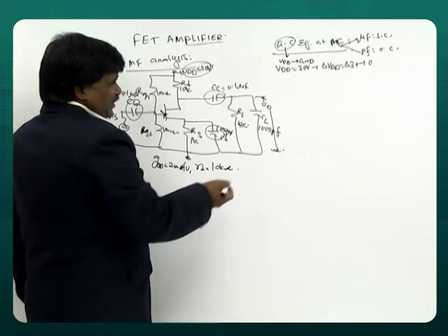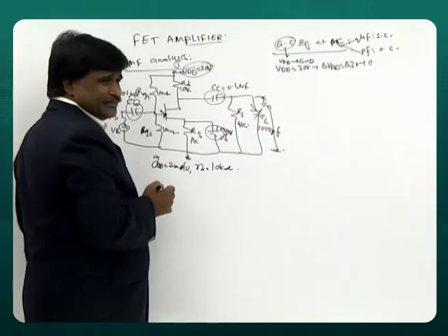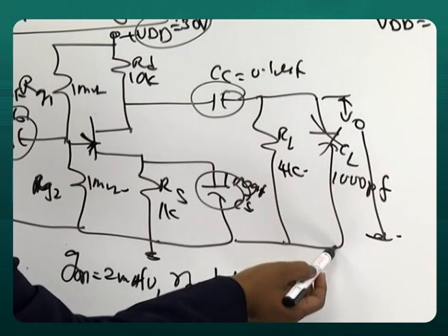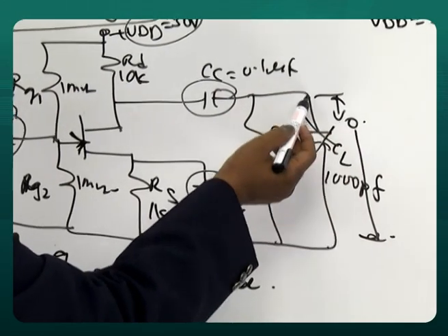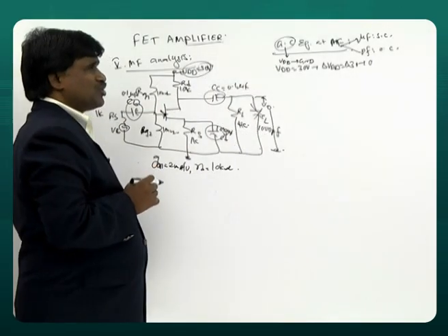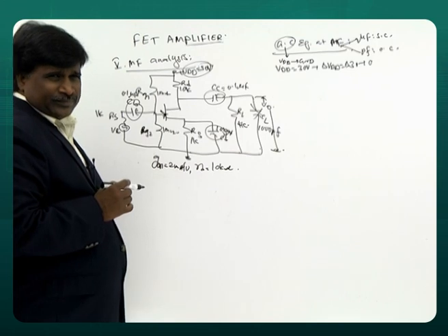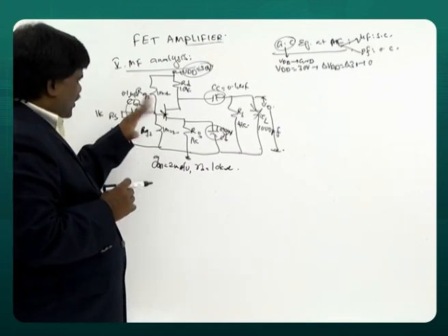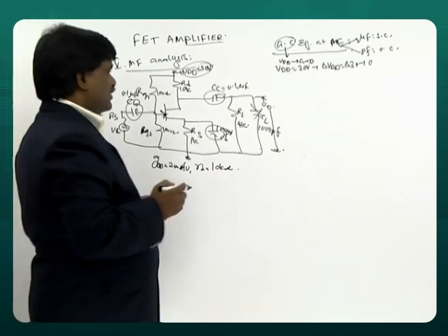And thirdly, picofarad open. Remember, by mistake, if you say it is short circuit, that's not valid because output is 0. Picofarad is open, microfarad is short. That's what is happening altogether. So shall we try to draw the equivalent for this situation?